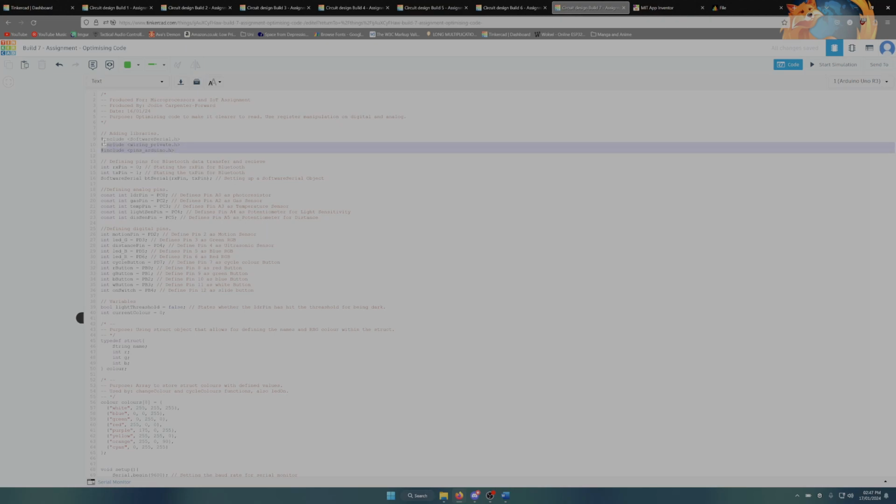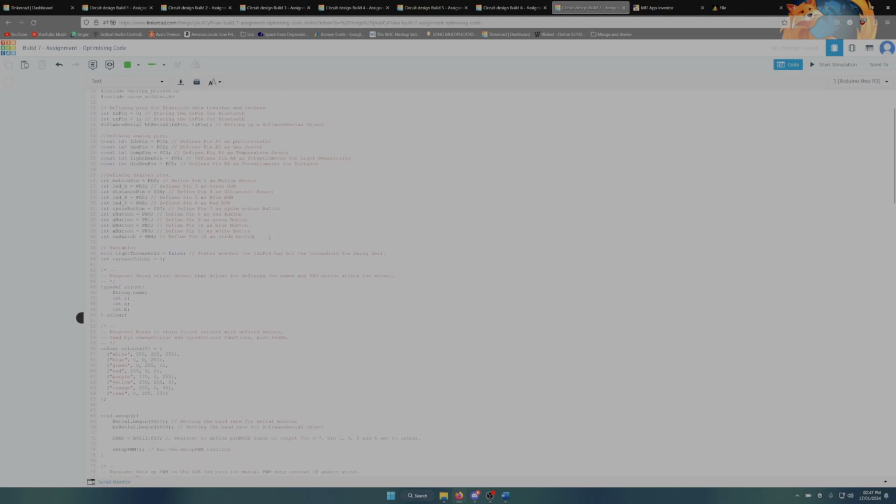To begin with, I added more libraries. These ones were needed for PWM and also the analog read and write functions. I'll describe them in a minute. From this point, nothing's really changed apart from here. Instead of actually defining the ports like pin 13, 12, all that type of stuff, I've used the registry. So we've got PB0, then PD2. When we're doing the port manipulation, I can call these instead of stating a number, so it knows how many increments the binary digit will have to move.